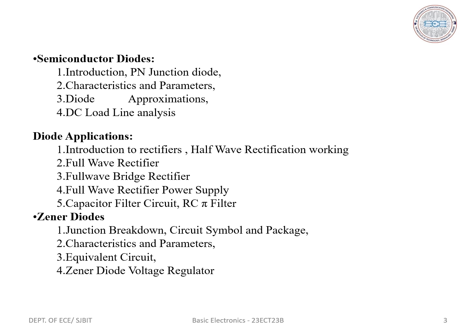A step-down transformer is a device that has two coil windings, primary and secondary, used to convert a high AC voltage, 230 volts at 50 Hz, to a required low AC voltage. A rectifier is a device with one or more diodes that converts secondary AC voltage to pulsating DC. A filter is a circuit used to remove fluctuations or ripple present in the rectifier output. Examples of filters are the capacitor filter, LC filter, pi filter, etc.